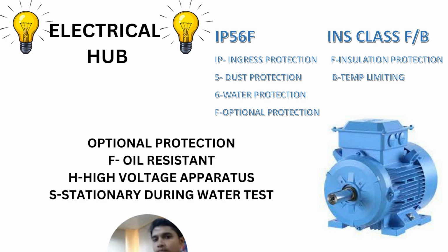For example, if you are operating a motor in a shed where there are no traces of water, or if certain water can come at certain times, then you don't need IP 59 or 69. So generally in the plant, IP 55 or IP 56 is preferred.